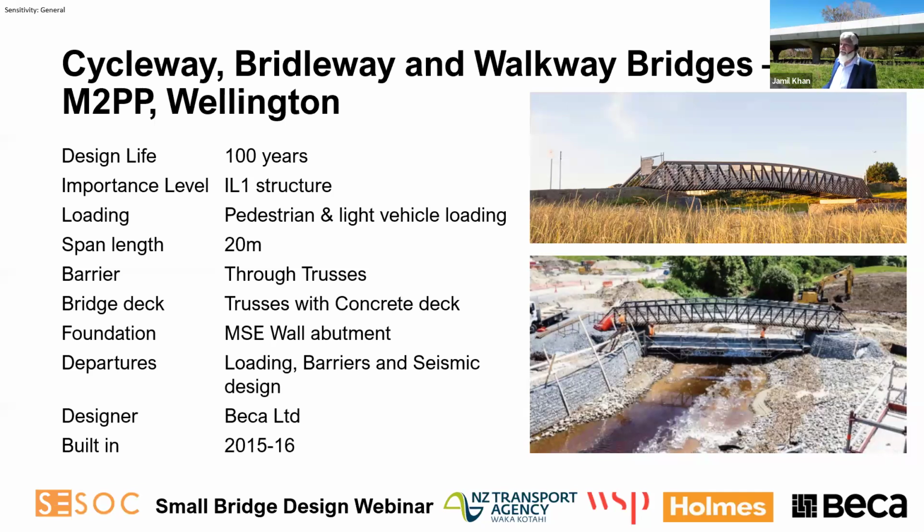Loading was only pedestrian loading and light vehicle loading, because the agency wants to use these bridges for maintenance vehicles only. It's not public vehicle access, only for maintenance purposes. They want to carry the maintenance vehicles, so we use a lightweight vehicles loading.